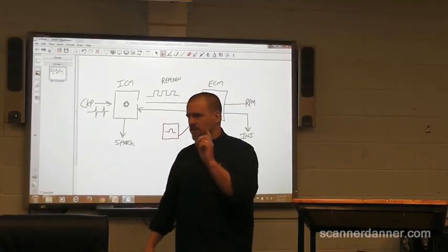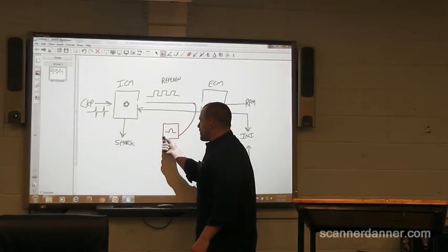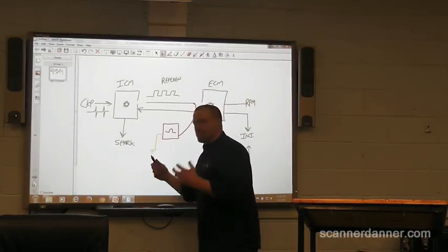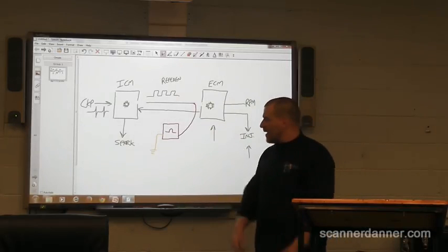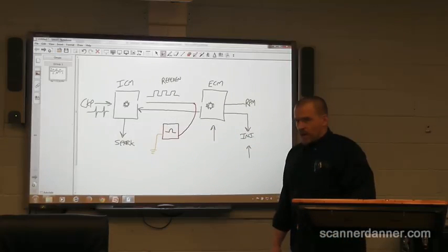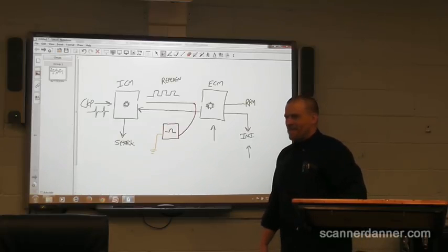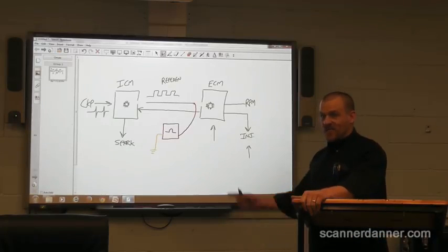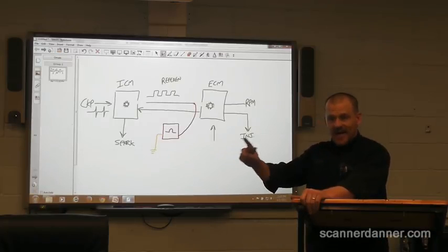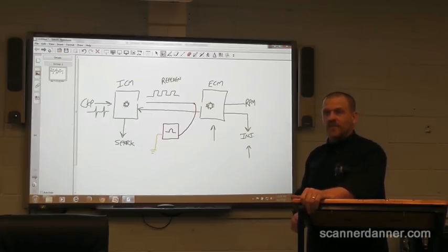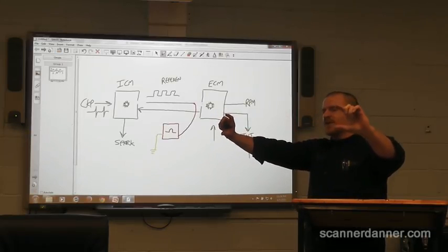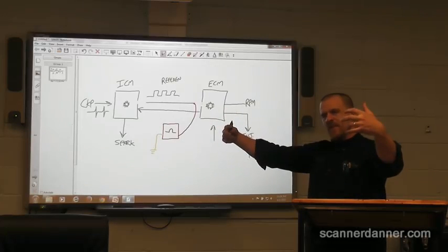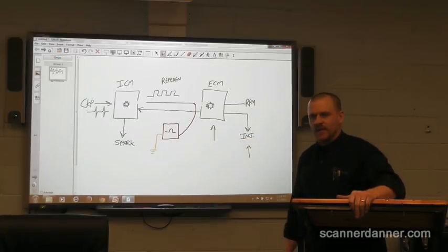One lead's got to go to the wire, and the other lead has to go to something metal on the car. The whole body of the car is your, quote, ground. Does it matter where? I mean, no. It really doesn't. Yes, it actually does. I've done this where most of the stuff under the dash, for example, is very good, but then I connected my meter up to this metal bar under the dash, not realizing that both ends of that metal bar were bolted to plastic. Yeah.